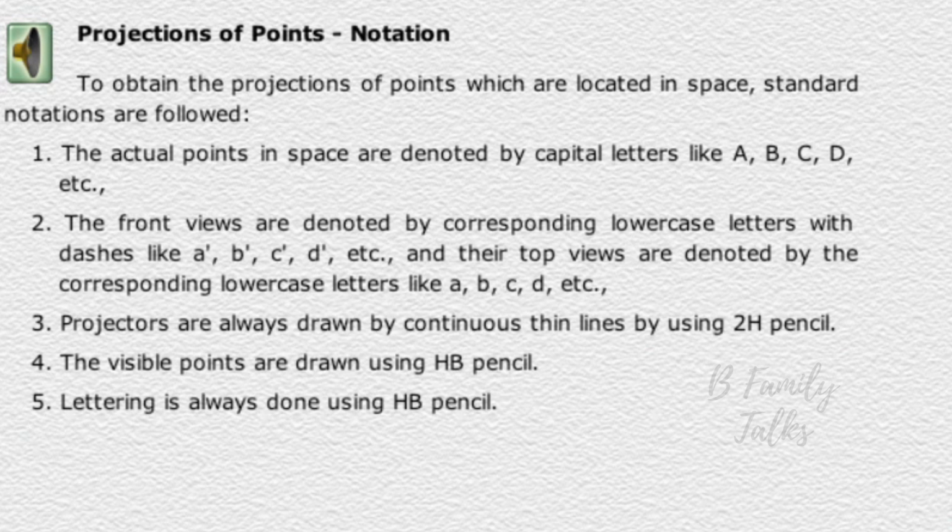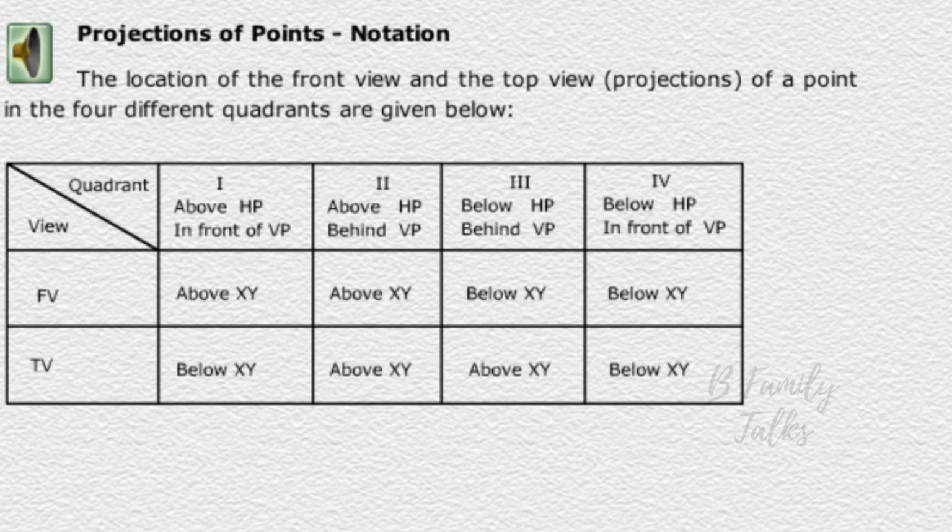Projectors are always drawn by continuous thin lines by using 2H pencil. The visible points are drawn using HB pencil. Lettering is always done using HB pencil. The location of the front view and the top view projection of a point in the 4 different quadrants are given below.